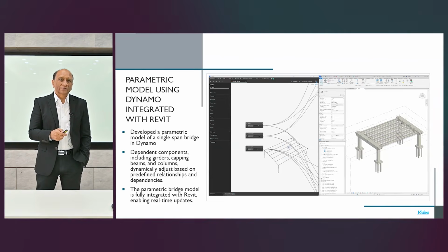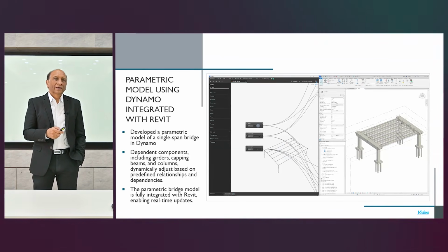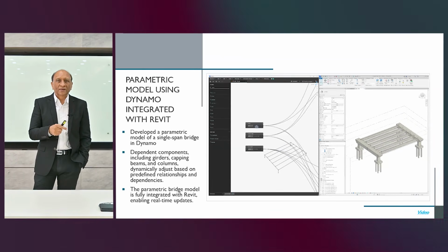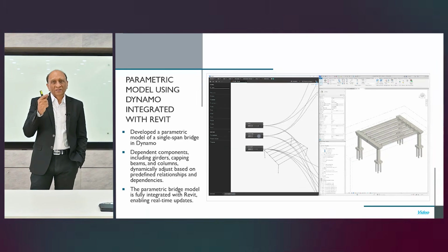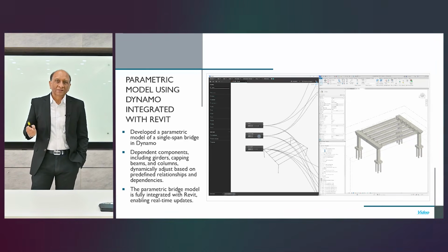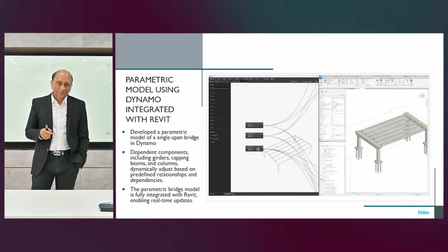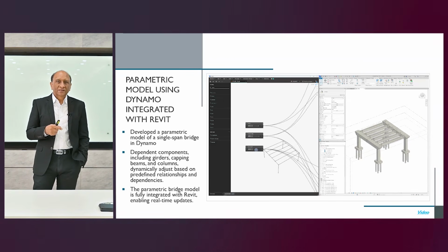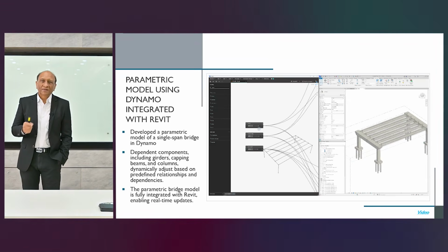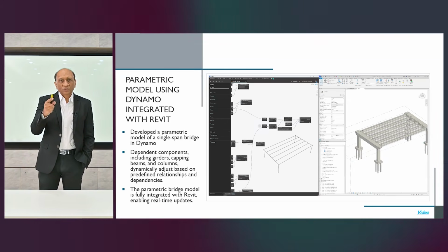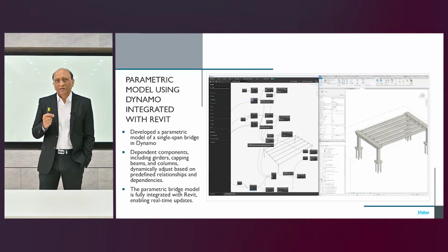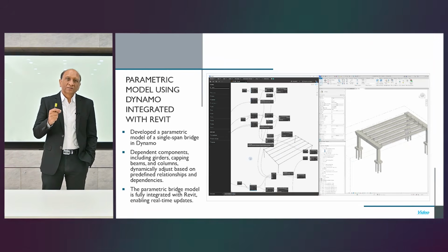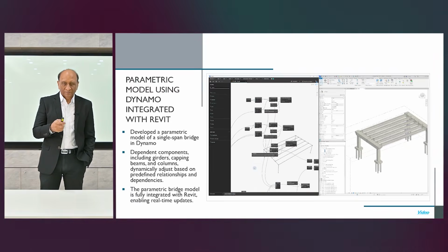For example, I give you a quick example of how this parametric model will work, where you define the parameters, you link them together, and once you change any parameter, the structure is updated quickly and completely by changing just one parameter. So you can change the weight, everything automatically adjusts. We change the length, everything adjusts. This capability of parametric modeling, parametric editing based on this flow gives us a great power to create very complex, comprehensive, but geometrically complete, consistent models.